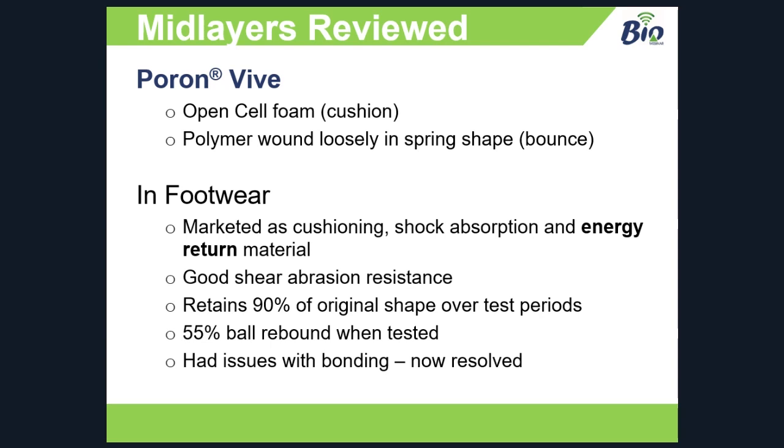I know personally as a lab here we had issues with bonding, and that was to do more with the polish. We had a shiny surface on one side which didn't allow some of the bonding to occur. We've now resolved that. So if you're having any of those where the mid layer is not letting the top cover or the base combine over time, it's unsticking, have a look at how shiny it is. Going forwards the suppliers have corrected that for us. So going through there.